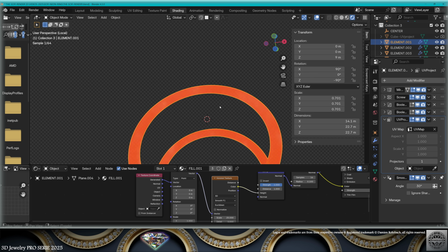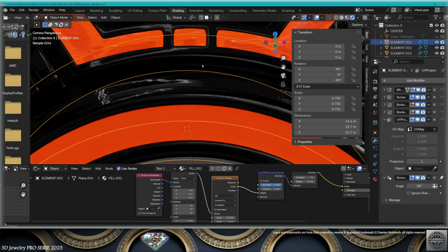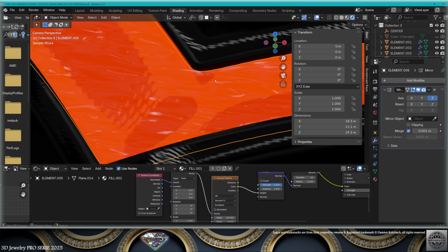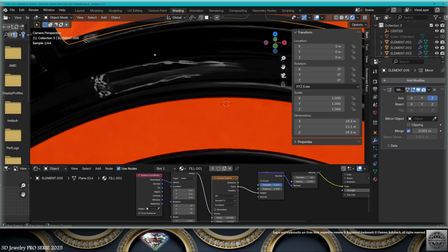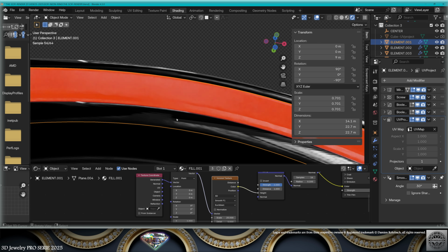Because here we can see that the scale of the Voronoi bump map texture is much different than maybe here on this element where we already see some slight waves as an effect of the bump, but on other elements we don't see much of the bump map, and that's because the mapping, the UV mapping, is different because the geometry is very different and the scale and the position, the orientation and all of that.